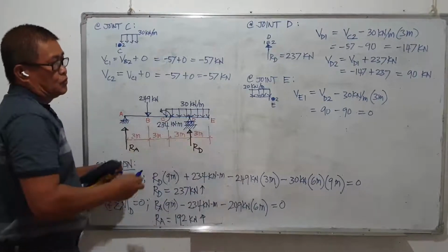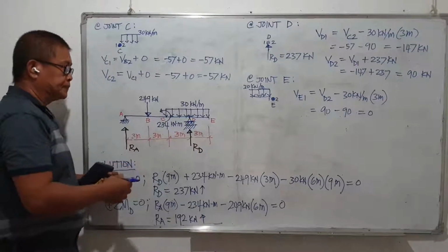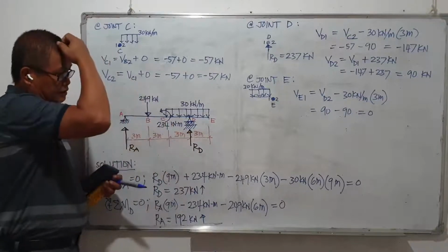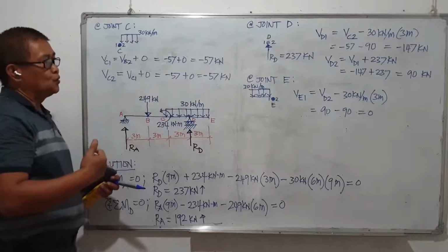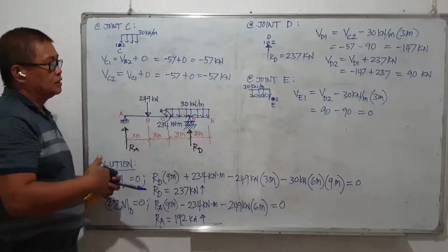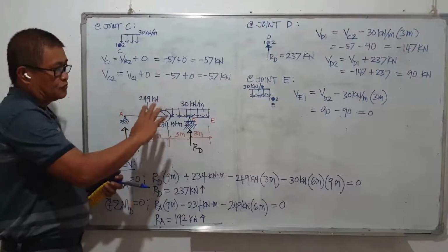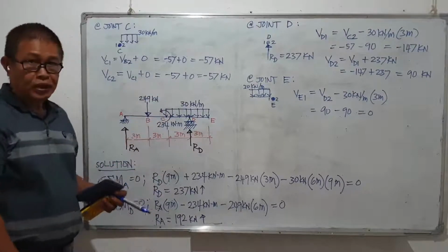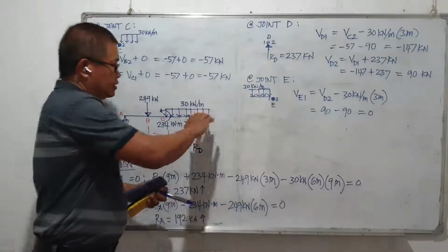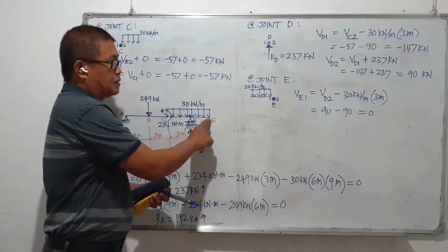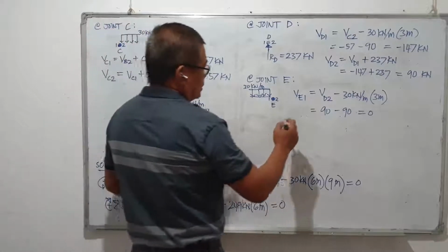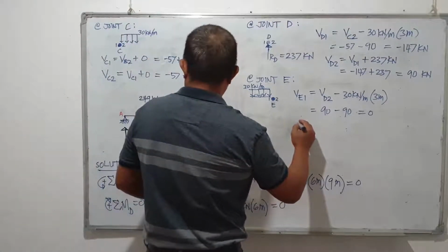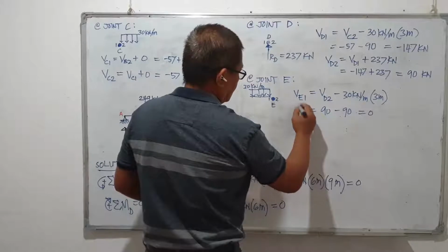So we have at least partially a value that will somehow confirm that the previous values of the shear diagram could be correct, because the shear at this point becomes 0. That should verify the results of the previous values.